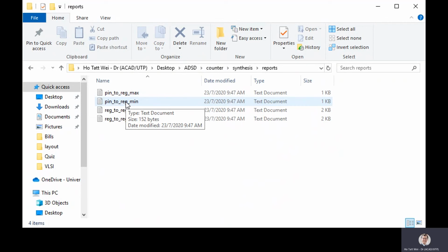It must actually have propagation delay longer than the min delay. Otherwise, you will have race conditions. That is, the output actually jumps through 2 flip-flops instead of 1. And you also have the max delay constraint, which is that the propagation must happen within less than a clock cycle minus the setup time. Otherwise, the flip-flop will fail to capture the value in the next round.